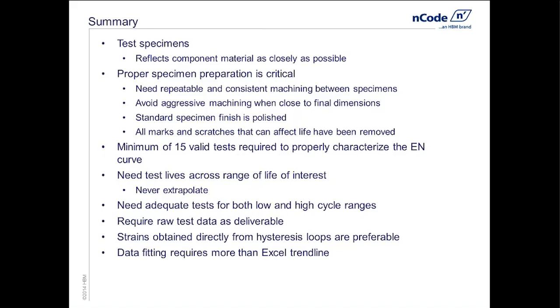We want to guarantee that the specimen is dimensionally correct, with minimal variation across specimens, and that it has a geometry such that when I apply a tension load, I'm not inducing things like bending because of misalignment of the specimen.